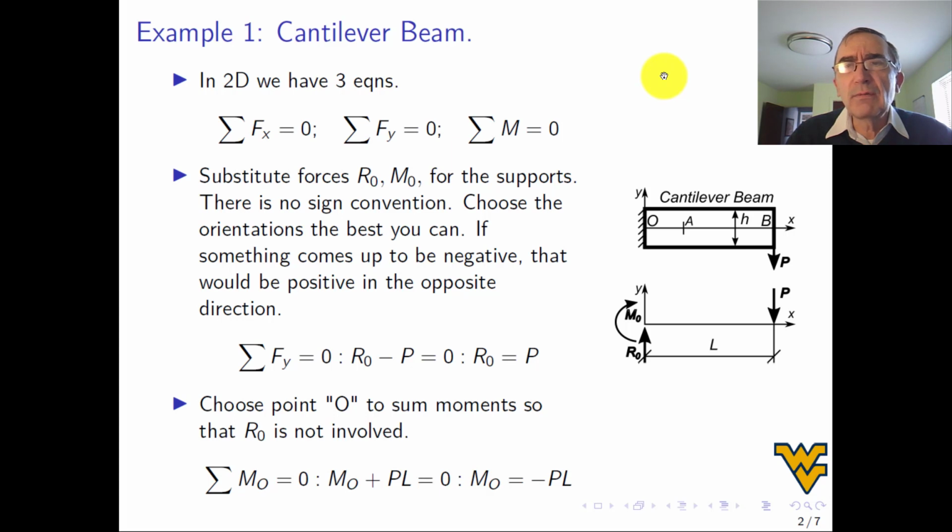Reactions and internal forces basically are the same. The only difference is that the reaction happens at the boundary of the structure and the internal forces are internal. But they are forces anyway, and you will see that in order to calculate them, we use the same method.